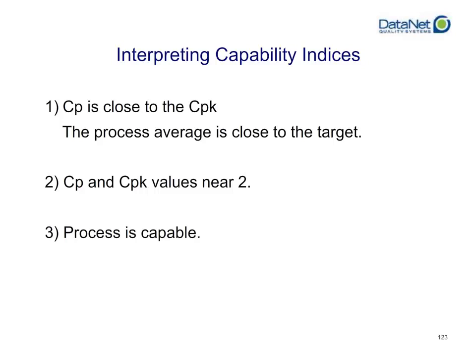Okay, now that we have calculated CP and CPK, what does this mean? The CP value is 1.94, which is pretty good by most objective standards. Now, I have no historical context. I don't know if this is better or worse than what you used to be doing, nor do I know how your competitors are doing. But at least I know that objectively, most industry experts would say you're doing pretty well on your capability, your CP.